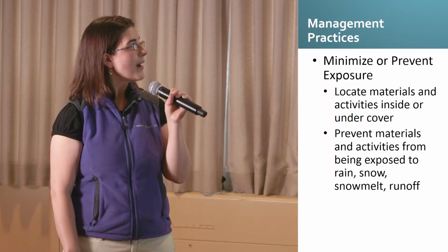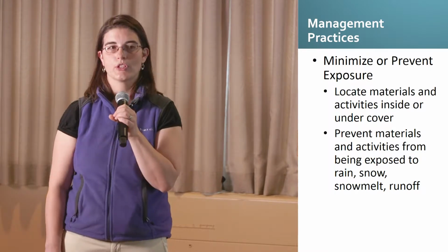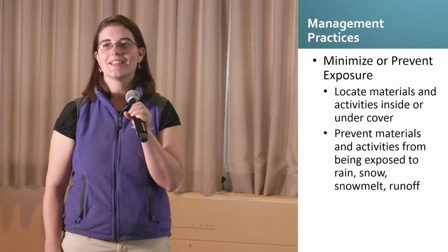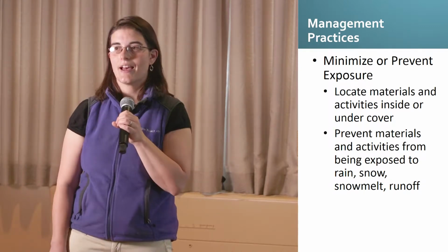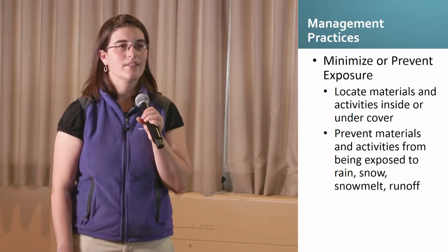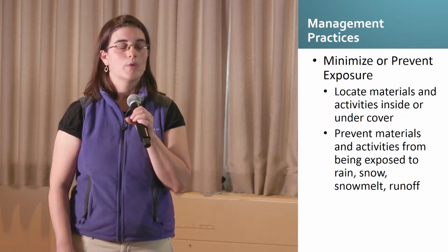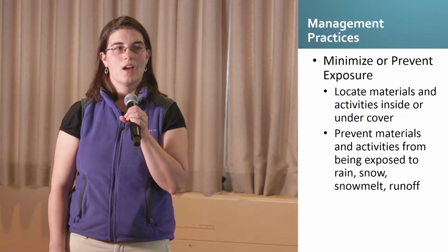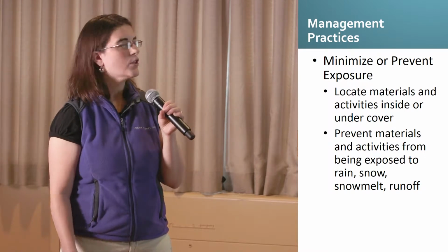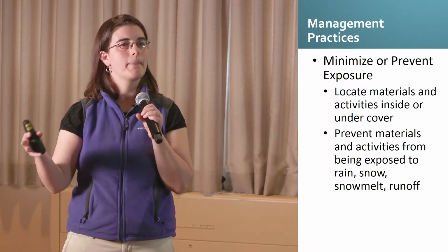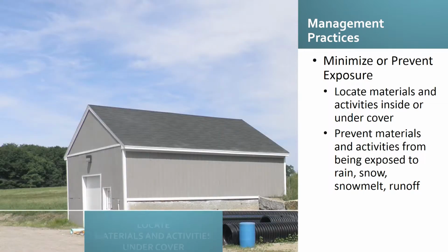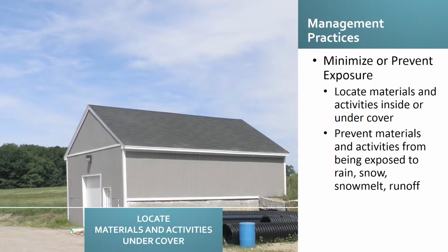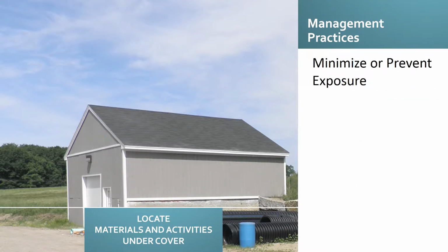So the first management practice is minimize and prevent exposure. It is what it sounds like. You want to locate materials and activities inside or under cover to prevent their exposure to stormwater, which would then prevent the creation of pollutants. If you can prevent the pollution, you don't have to manage the pollutant. So you prevent materials and activities from being exposed to rain, snow, snow melt, and runoff.